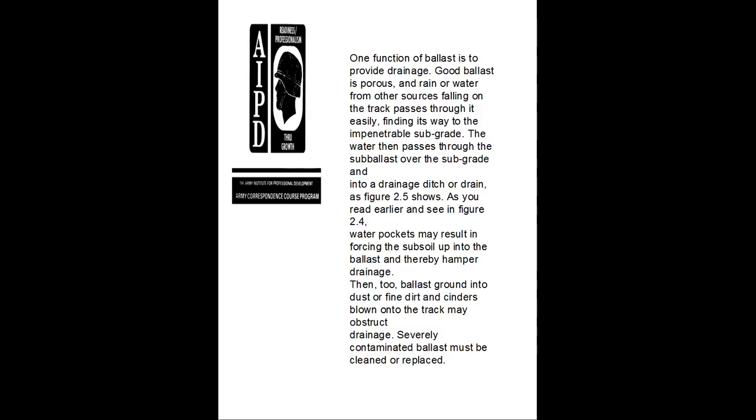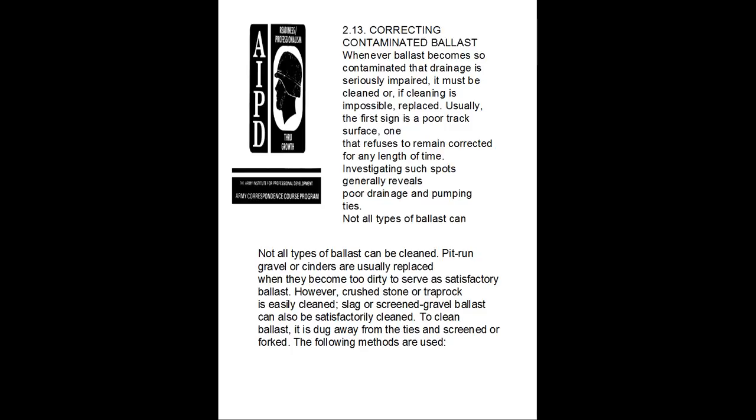See figure 2.4: water pockets may result in forcing the subsoil into the ballast. Drainage may also be hampered by ballast becoming contaminated with dust or fine dirt. Cinders blown onto the track may obstruct drainage. Severely contaminated ballast must be cleaned or replaced. 2.3 Correcting contaminated ballast.